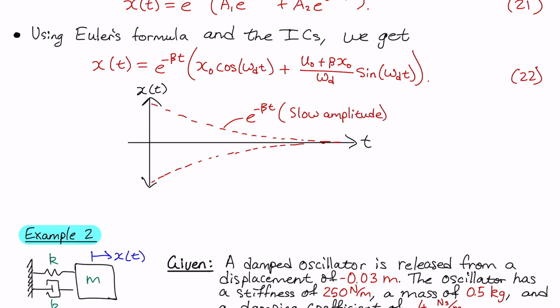You won't really see this terminology in the study of linear systems like what we're looking at right now, but it does pop up frequently in nonlinear systems. In fact, it's a fundamental property when studying nonlinear vibrations. We talk about slow oscillations and slow amplitudes. What the displacement signal actually looks like, and we're assuming 0 initial displacement, is that it starts from 0, rises up, hits that amplitude, comes down, hits there, and oscillates until it damps down to 0.